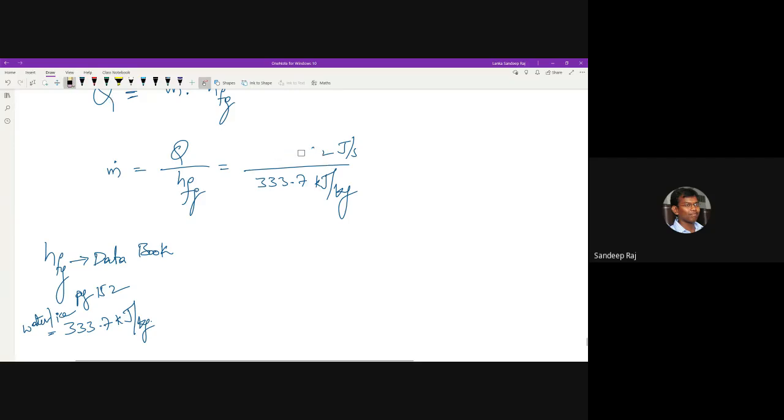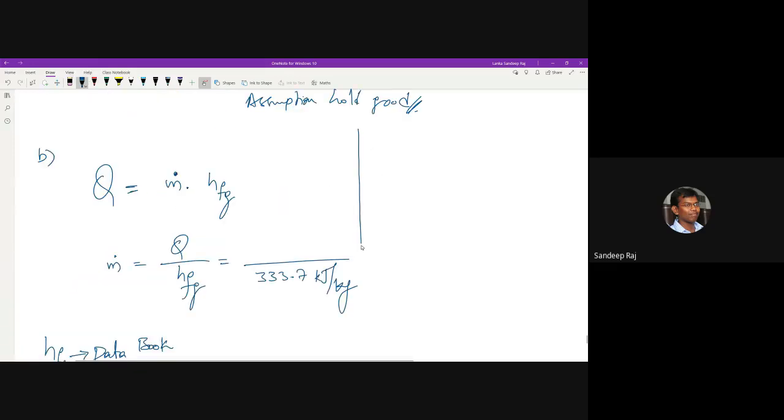let me take out this from here, and then if I have to get this Q here, let me write this as Q dot or some different Q. This Q dot is equal to Q into the time that you have to take. Okay, the time is 24 hours. This is 8058.62 into the time, 24 hours into 3600 seconds, so that this value will be in joules now.